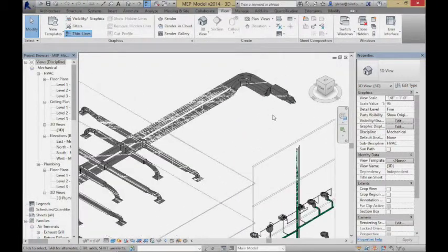in something like an air handler unit, which will be back over at the back end of the system, which has fans which take all the air that has come to it, do some sort of processing of the air, whether it's introducing fresh air or adding some heating or cooling at that point, and recirculate the air back through. So in a typical building, we'll often have these different registers, some of which are supplying air, some of which are returning air, but ultimately are going back through a return air system.